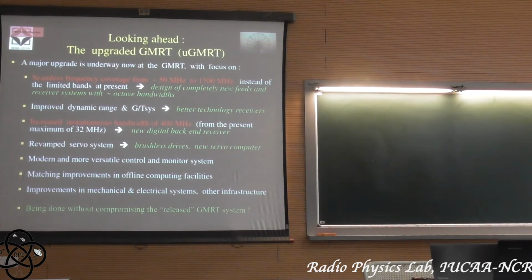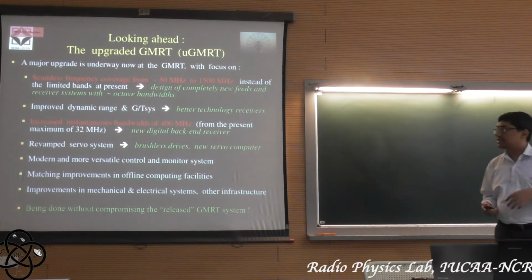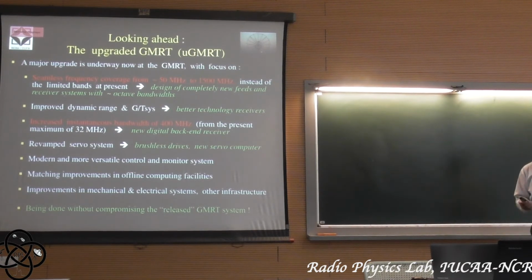So you can see now the problem is those feed elements at the focus. You have to come up with a new design which can really pick up a large range of frequencies. Okay, and then the rest of the electronics has to be able to handle a much larger range of frequencies. So that's a major challenge in terms of design of completely new feeds and receiver systems with large bandwidths.